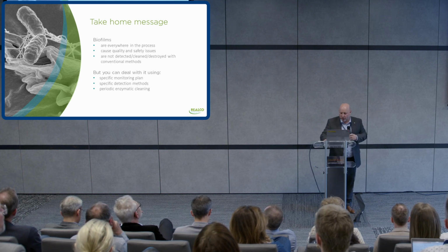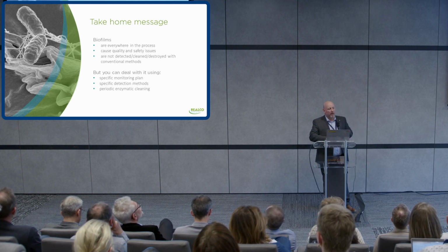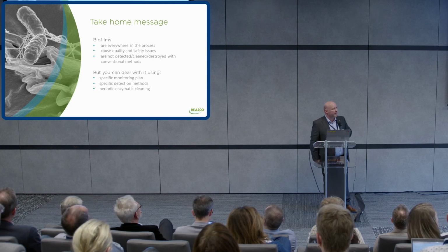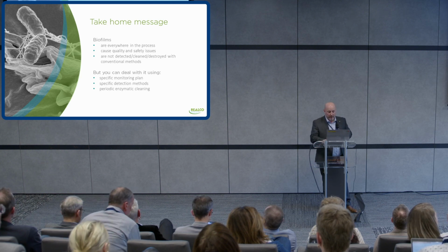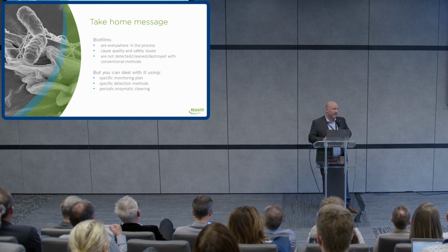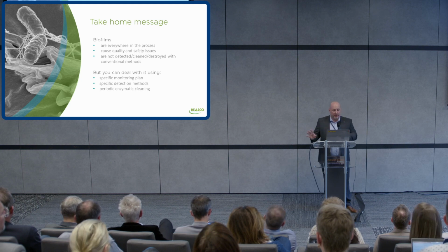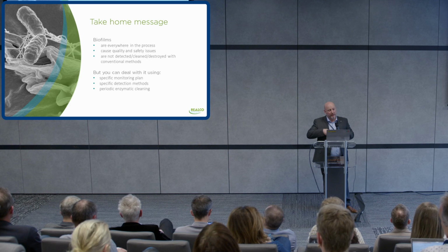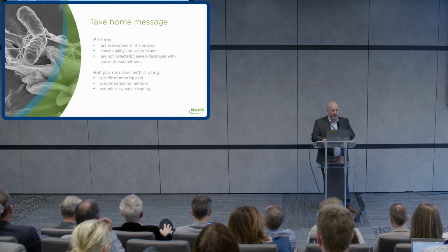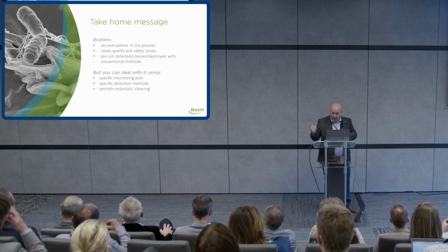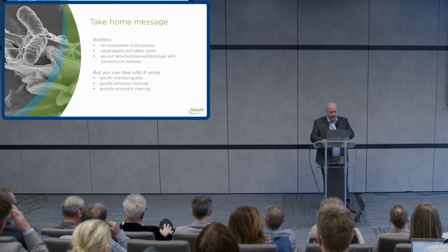Take-home message. Biofilm can be everywhere in the process. They can cause quality and safety issues. They are not detected by standard sampling methods, and they are not always destroyed by caustic and acid products. You sometimes need to reinforce your cleaning if you want to deal with biofilms. But you can deal with biofilms by using a specific monitoring plan. Thermophilic bacteria, for example, in the last example.